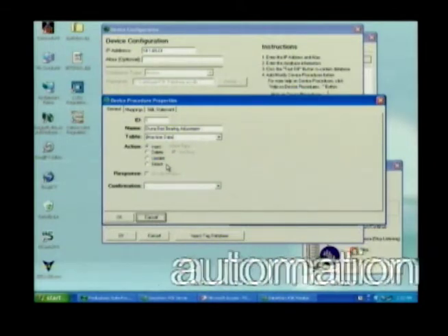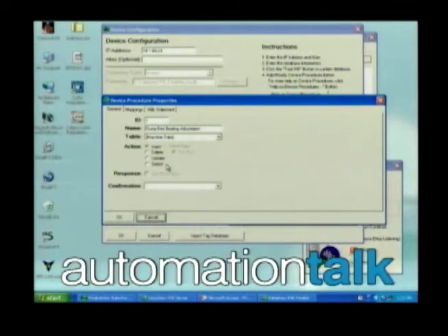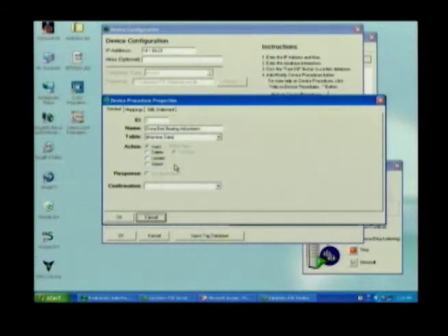So in our case, we're going to populate this database with all the VIN numbers of the trucks, get an end bearing distance reading, and a temperature, and someplace down our production line, somebody else is going to select that record to get that information, and the calculation is going to tell them how to adjust the preload on the bearing. So in our case, I named this dump bed bearing adjustment.